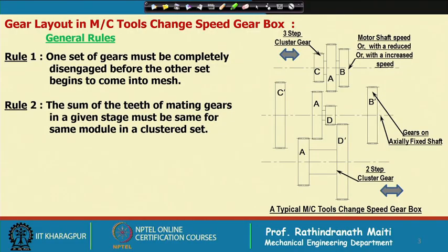Also another issue is there, while we are selecting the ratio. In case of general purpose gearbox, we do not go for exact ratio to avoid tooth hunting, whereas in case of machine tools we need not follow that strictly. Also, as precision gears, all gears are usually hardened and ground for long life, they are also lapped. That means, for very good machine tools, they should be super finished.